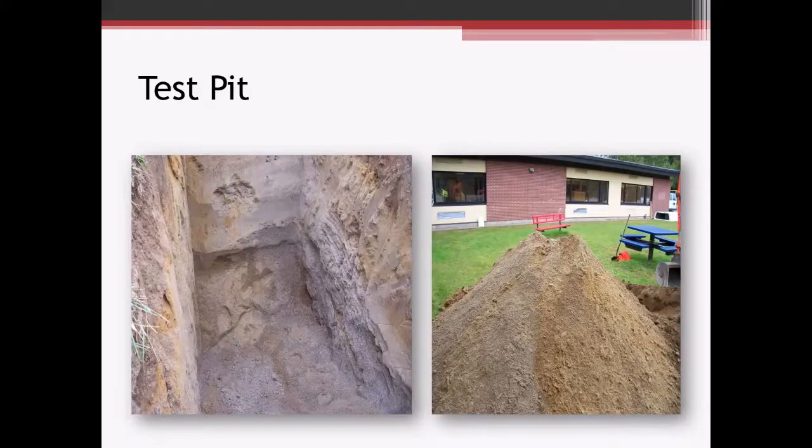Test pits, as I mentioned, are typically going to be dug with an excavator, and they're going to give a pretty good representation of the soils to shallow depths, as well as the groundwater conditions. And these are usually limited to about 8 to 12 foot in depth, depending on the size of the excavator. One of the downsides of these is they do disturb a very large area versus a soil boring.